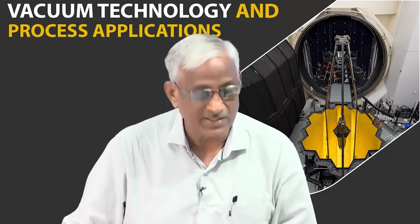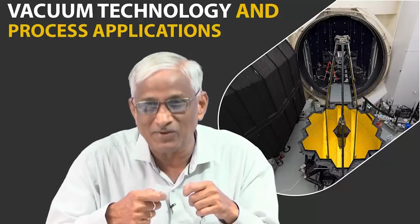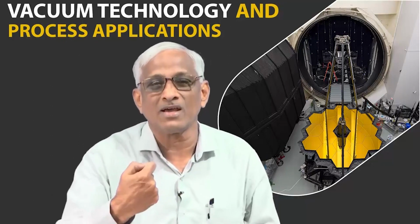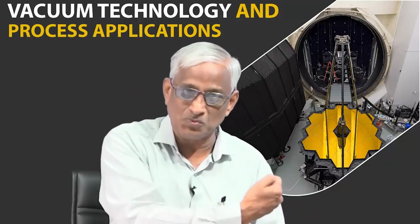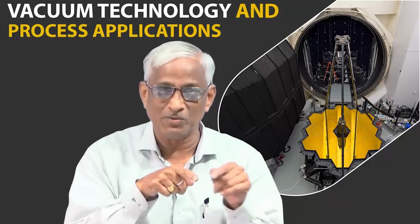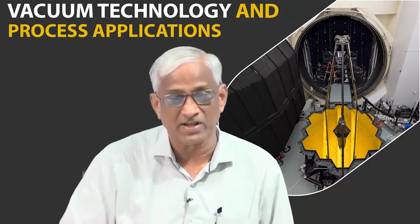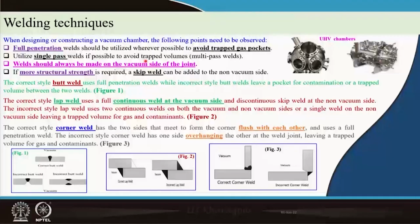Okay. And single pass he should do, that is another thing. You cannot do it for some time and go out and have a tea and then come back, because that starting point will be difficult. The torch has to move continuously, in one continuous circle, otherwise there will be discontinuities in that, which is very dangerous. It creates pockets of gases. So, single pass welds are very important.